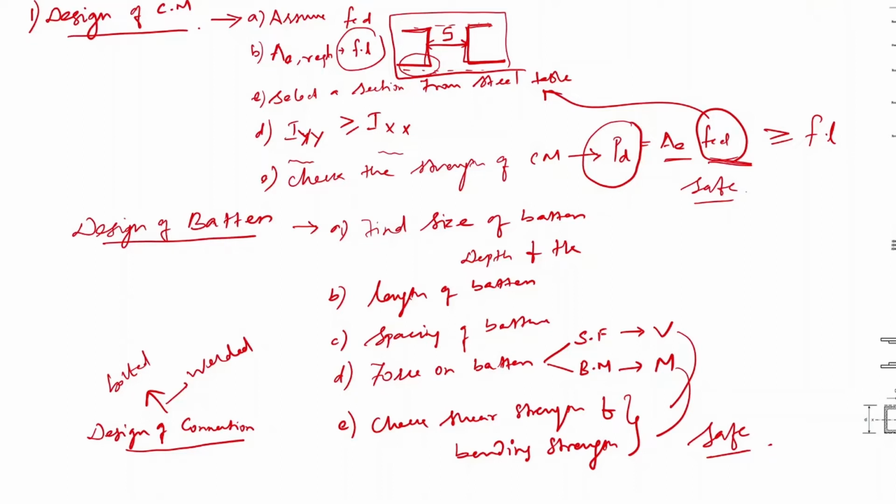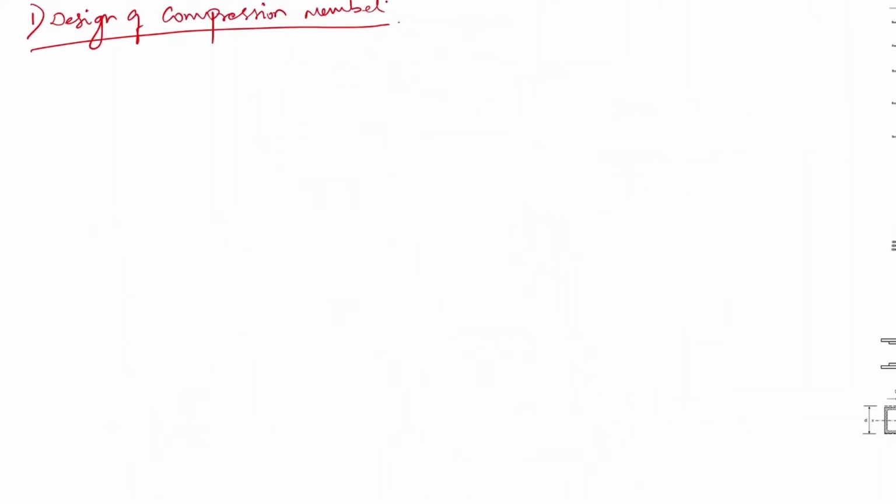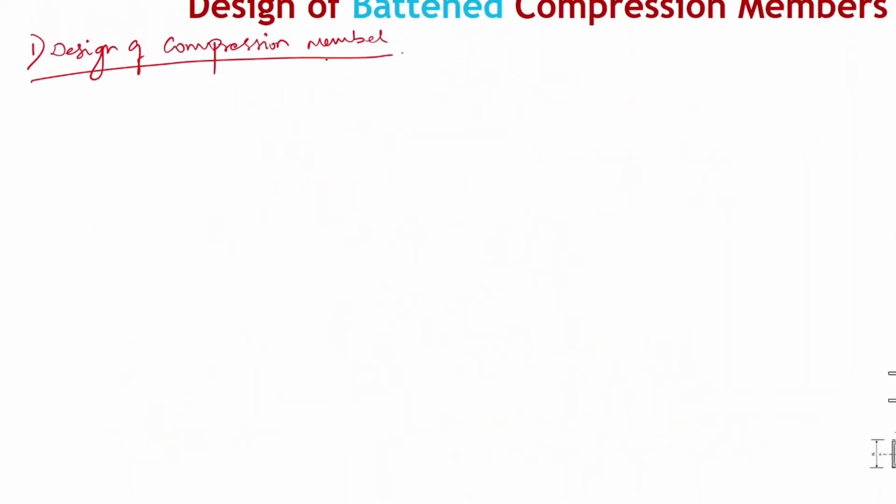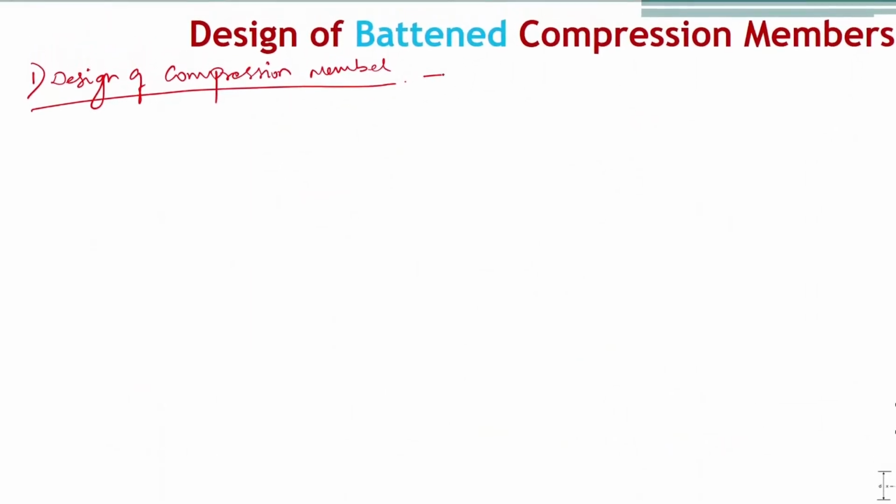Let's solve this numerical step by step. First, we need to design a compression member. In that, you have to assume the design compressive stress. We'll assume that as 160 Newton per mm square.